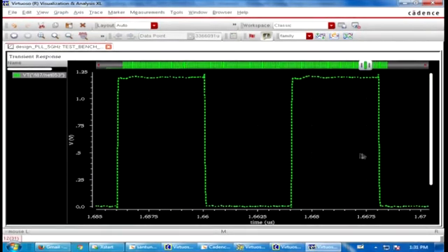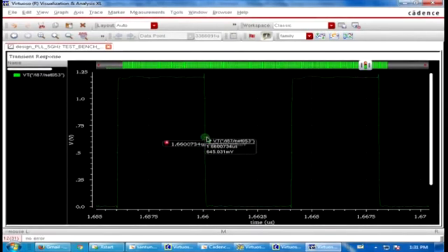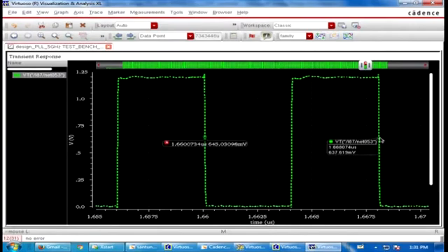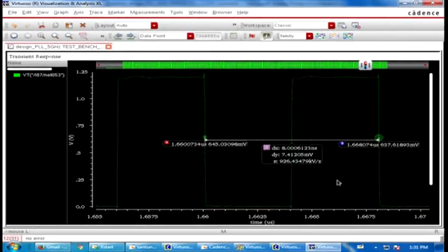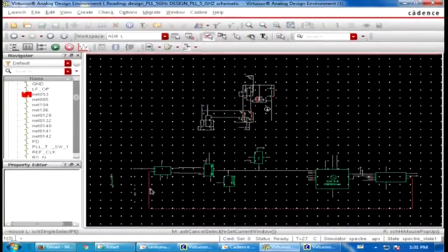Our reference frequency is 125 megahertz. It is also 125 megahertz. You can see that from 5 gigahertz, it is divided by how much? See, it's almost 8.000061 nanosecond. That means 1 by 8 nanoseconds is 125 megahertz. It is going to 8.00006. Yeah, it's almost locked. So you understand the divider, right?